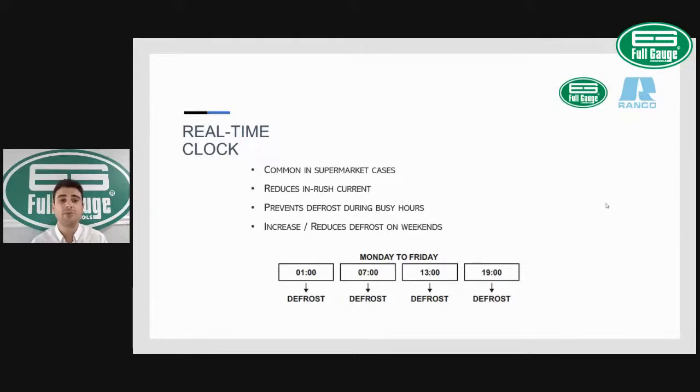So by setting the real-time defrost clock, you can actually reduce inrush current as well as prevent defrost during the peak hours. For example, there is a restaurant which opens for breakfast and lunch. You don't want your defrost cycles to take place at 8 o'clock in the morning when the restaurant is busy serving breakfast. Neither do you want the defrost taking place during lunchtime when the restaurant is busy serving lunch.